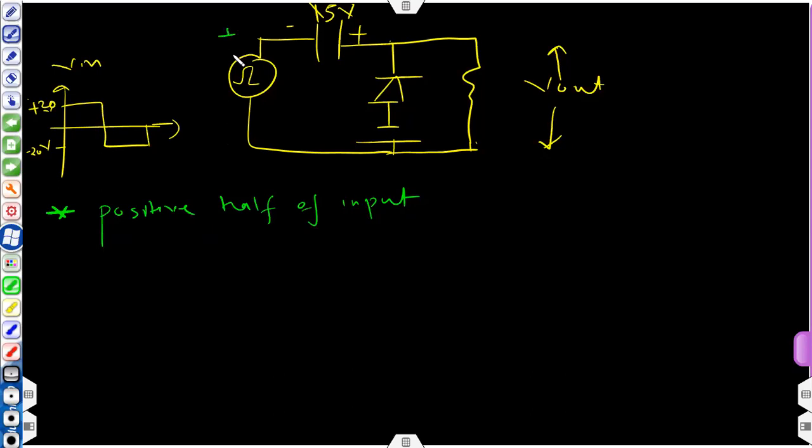okay, plus will be at the top, minus will be at the bottom of this voltage source, and this is minus plus 5. Okay, so this combination of the input voltage sources is forcing your diode to be in the reverse bias state, negative connected to P side and positive, both these positives will add up, and positive is connected to N side. So diode is reverse biased, and a reverse bias diode is considered as off.